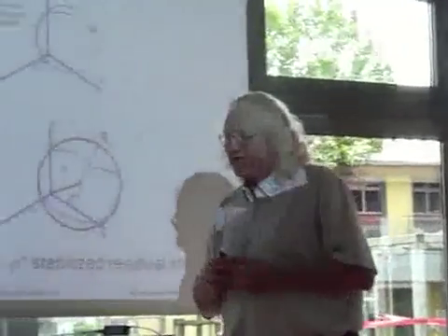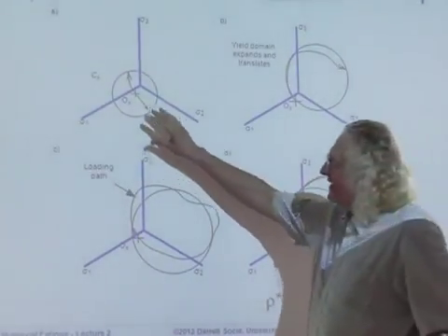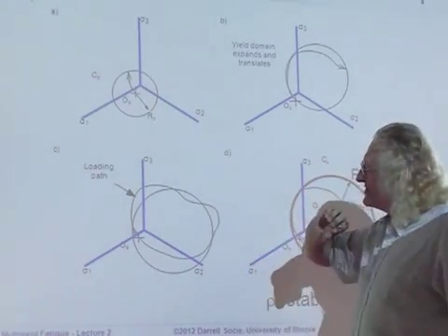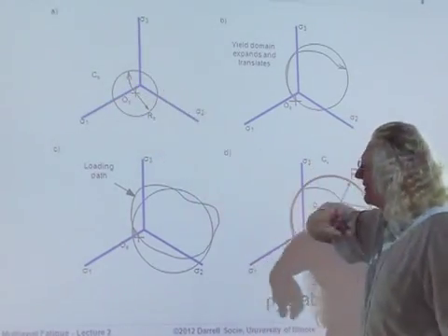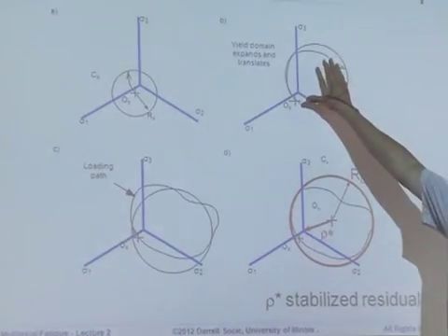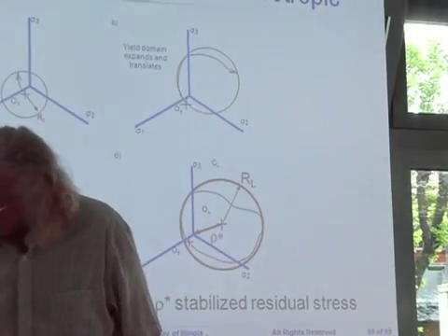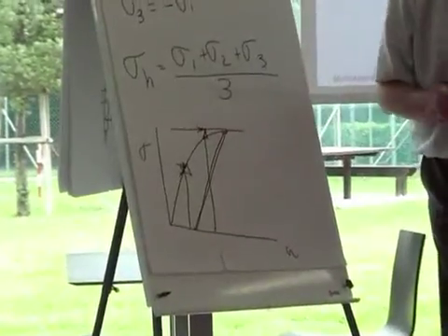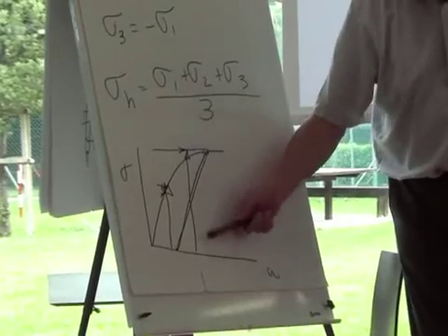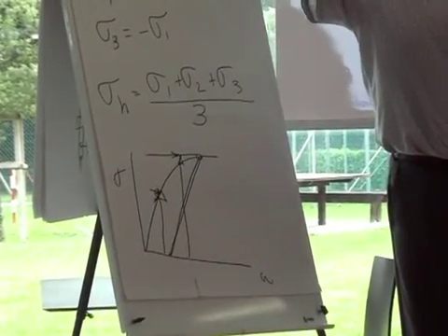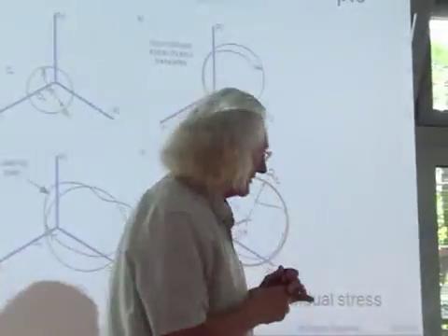Okay, so then we have to worry about things like mean stresses and so on, and these spheres can move around in space. But as I continue to load it, these spheres, which just give me the combinations of stresses and move around in space, also expand in size, and that essentially corresponds to increasing the radius. The idea behind Dang Van's theory is that I just need to know what is the critical distance here, what is the critical stress range that I can have, and that will be dependent upon the history. How big this sphere can grow, that's the basis of it.